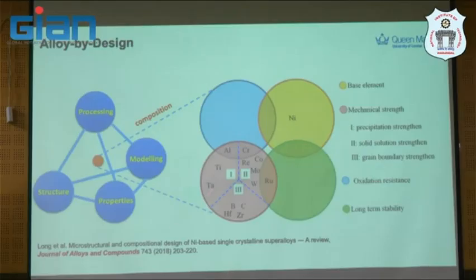I didn't have a microstructure here, so I will just say it verbally. The gamma prime, in the homogenized condition, forms a cuboidal structure, surprisingly, due to the crystallographic orientation and relationship. It is the L12 phase compared with FCC. For grain boundary strengthening, you may have heard about using boron to decorate the grain boundary.